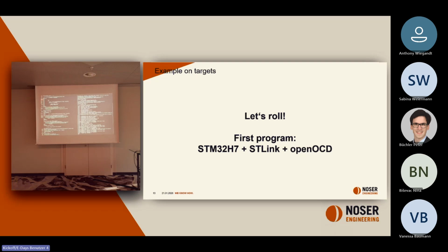Which means now, actually I could do an alias. I already prepared them, which means, for example, I have a GDB alias here, which means run GDB, take this GDB init file, and please load my ELF file. So it means if I run a GDB, connect, load, ready. Which means now with just two command lines, I just replace the other IDEs. You don't need any IDEs here.